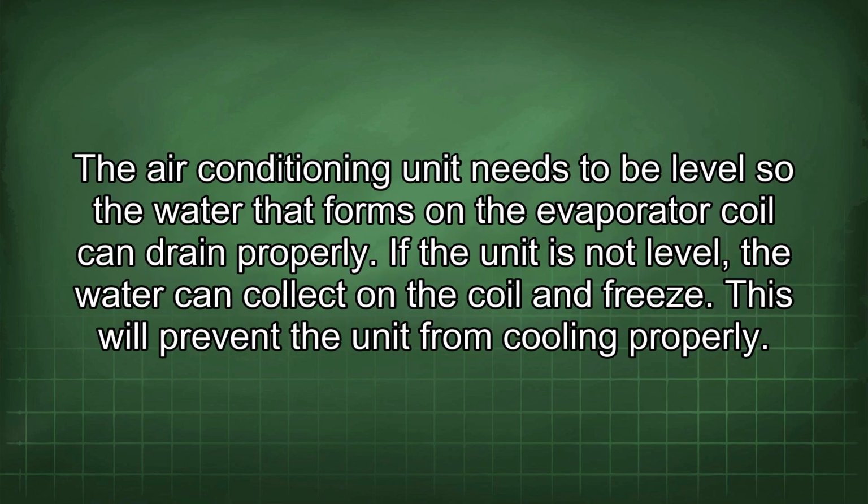The air conditioning unit needs to be level so the water that forms in the evaporator coil can drain properly. If the unit is not level, the water can collect on the coil and freeze. This will prevent the unit from cooling properly.